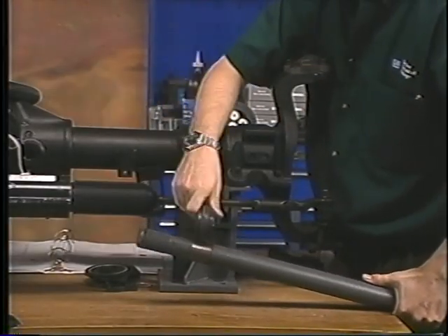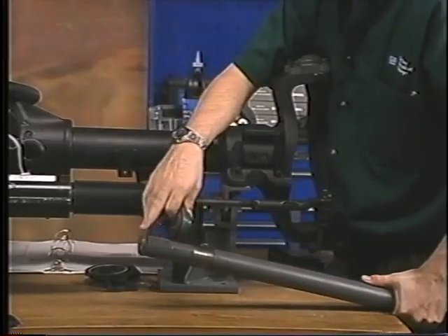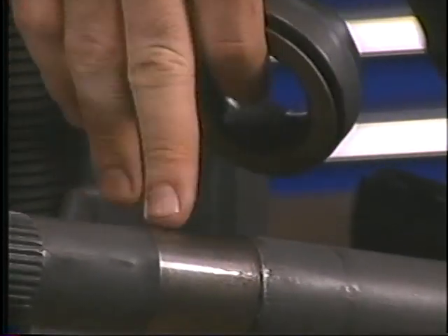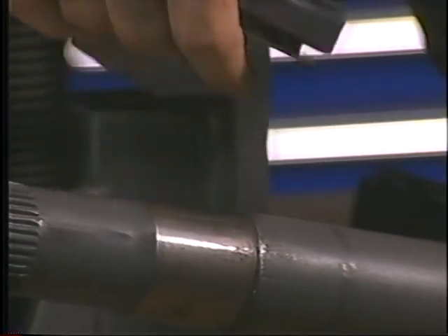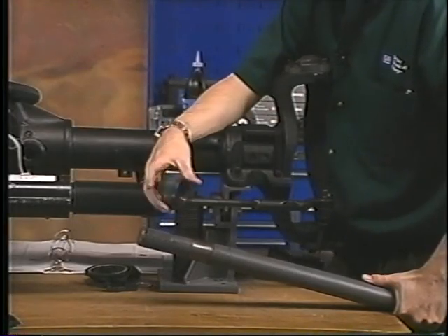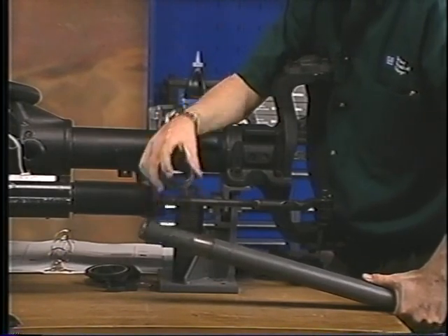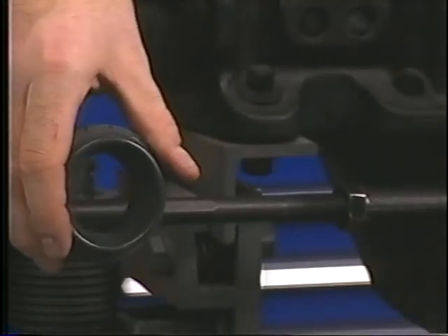Right there in the axle housing, right there on the polished portion of the shaft. Here are the splines. You get an idea where it's at. It's going to keep all axle fluid from this point inwards. Now, there's that seal. It's a pretty unique seal. We're going to take a closer look at it here in just a moment. Like a two-piece seal. It's got 3 sealing surfaces. Let's keep looking at some other things here.